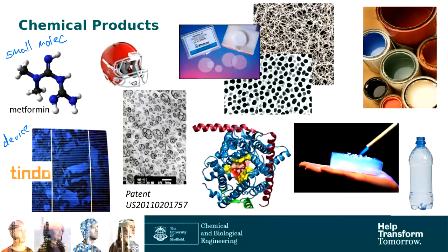It comprises high-impact polystyrene, which is the microstructure that you're seeing in SEM underneath the helmet. And these little bubbles, these are actually polystyrene domains, and they're dispersed in a matrix of butadiene. Now, polystyrene is really hard. If you think about a CD case, that's usually polystyrene, and it's hard and brittle.